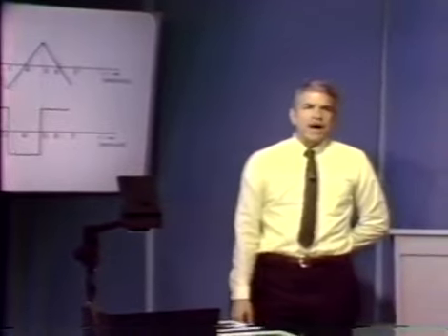The reason for the popularity of this technique as a function generator is that it's quite an easy circuit to implement. The Schmitt trigger can be done with a comparator of some sort, and the integrator, of course, uses an operational amplifier with a capacitor in the feedback path and a resistor as the input element to mechanize the integration. The nice part about it is that the frequency of this configuration can be changed by adjusting a single component.